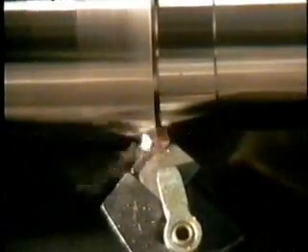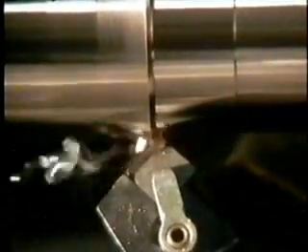The material from which a cutting tool is made must, to be effective, possess certain properties. Red hardness, abrasion resistance, and toughness are essential. A cutting tool must of course be harder than the workpiece it's cutting, otherwise it won't cut. It must also remain hard even when operating in conditions of great heat. The ability of a cutting tool to retain its hardness at high temperatures is known as red hardness.